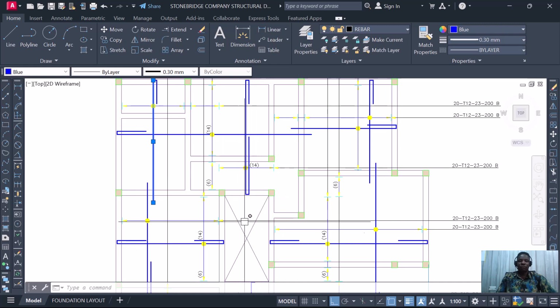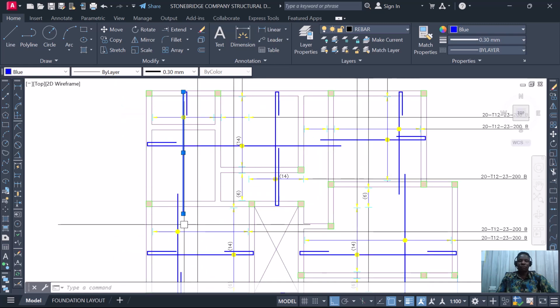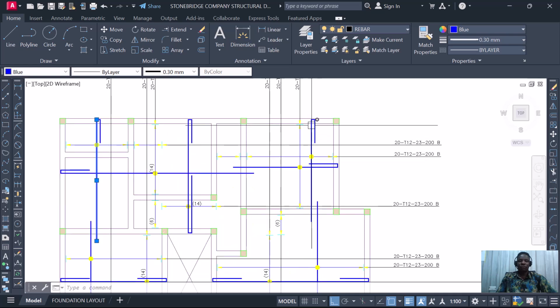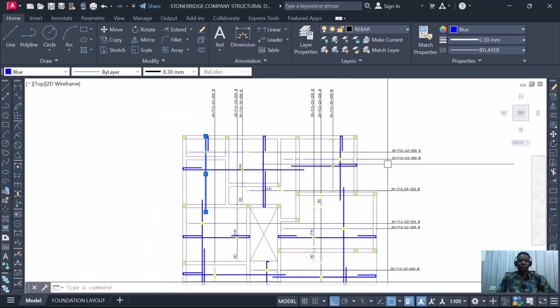So this particular beam, this particular rebar is expected to run from this span down to this area and stop. Then this other one has to continue, that's why you see the reinforcement over here. It has to continue down to this area because of what? Because of this void. This reinforcement has a different pattern because of the shape factor. You can see this other reinforcement running from where this rebar is going to stop.